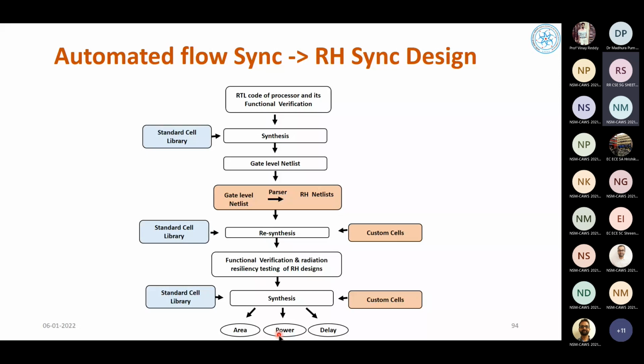This file is converted into a switching activity file. This is a very important step because if it is missed, then the power calculations are all messed up. If any of you are doing ASIC design or trying to use a design compiler, this is a step that we initially did not understand what was going wrong, and it took some time for us to figure it out.